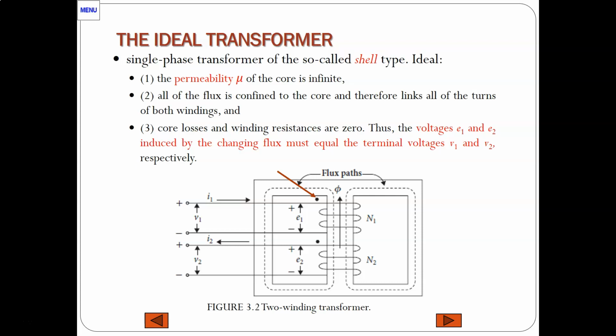Usually we do not know the direction in which the coils of a transformer are wound. One way to get winding information is to place a dot at the end of each winding, as you can see in the figure, such that all dot ends of windings are positive at the same time. That is, the voltage drops from dotted to unmarked terminals of all windings are in phase.